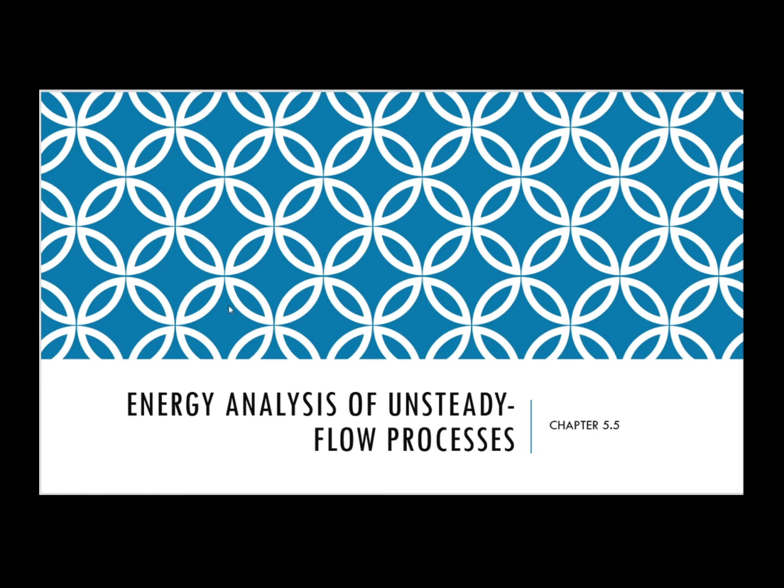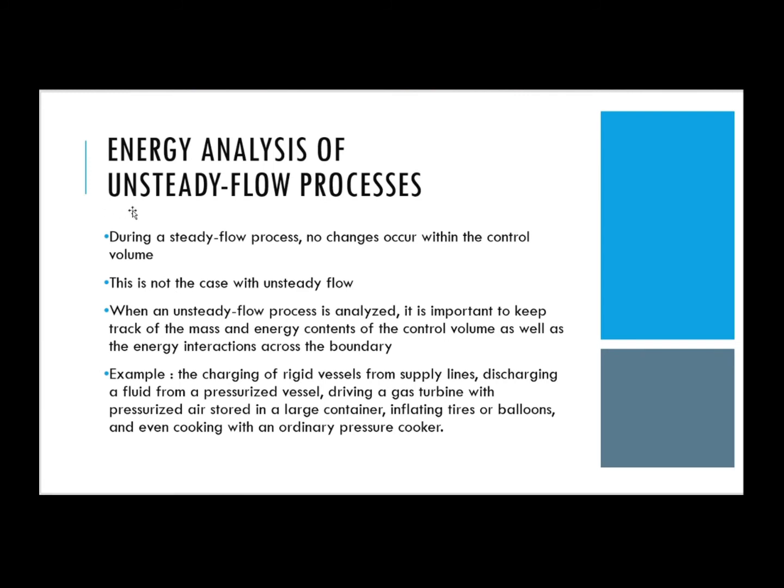Today I'm going to talk about energy analysis of unsteady flow processes, which is chapter 5.5 in thermodynamics. During a steady flow process, no changes occur within the control volume, but this is not the case with unsteady flow. When an unsteady flow process is analyzed, it is important to keep track of the mass and energy contents of the control volume as well as the energy interaction across the boundary.